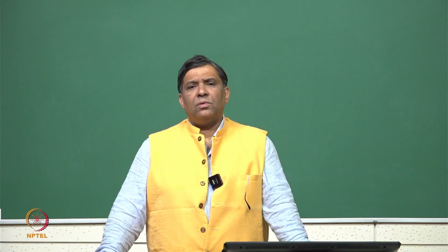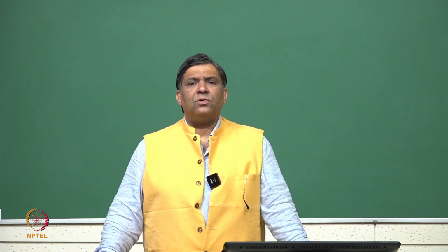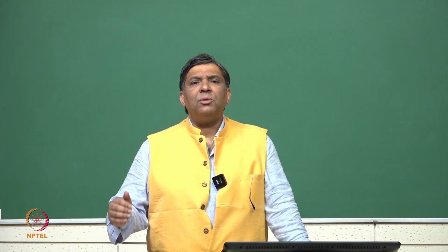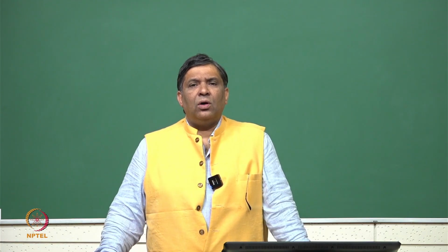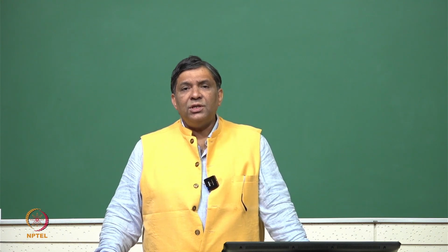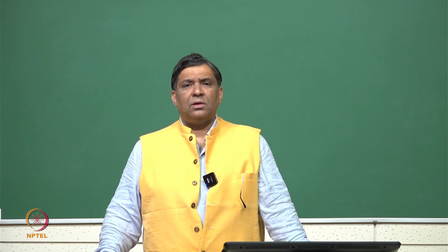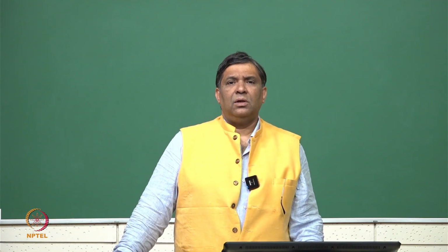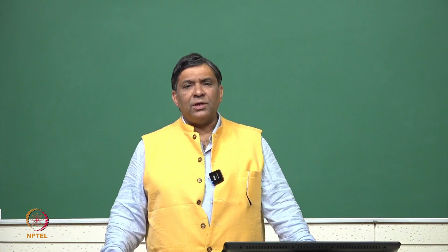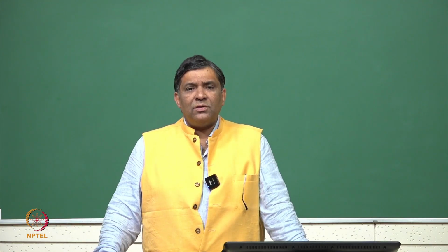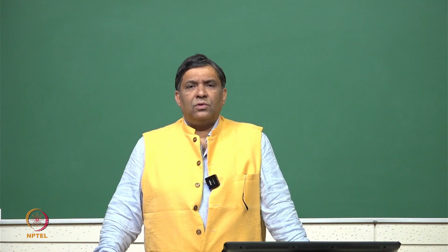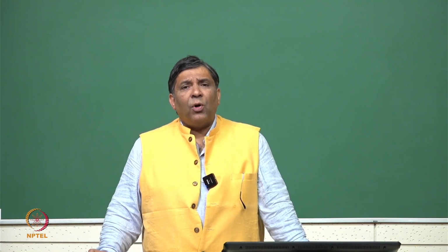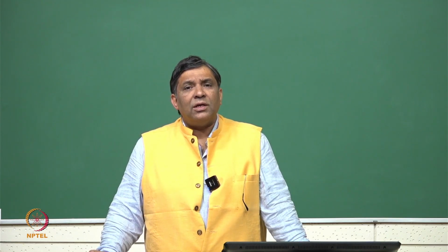And then we discussed what are the requirements of a good emission, and we have seen certain properties of the material which are essential for a better thermionic emitter. In fact, today we will discuss in detail about different materials. So, one property which is the most important for a thermionic emitter material is the work function.